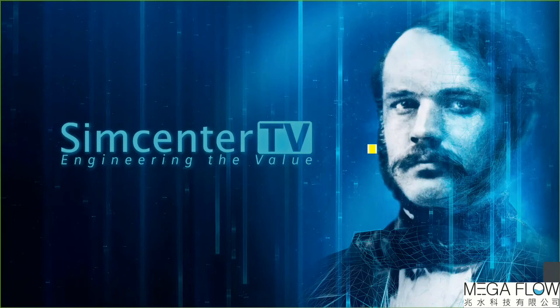But again, they were running DES with, I think it was 2.5 E-4 seconds as a time step size. So really a small time step size. And they were using MRF with tangential velocity, and they got very good results. But again, the pragmatic approach, 1 millisecond as a time step size, is in combination with MRF and tangential velocity. Yes.